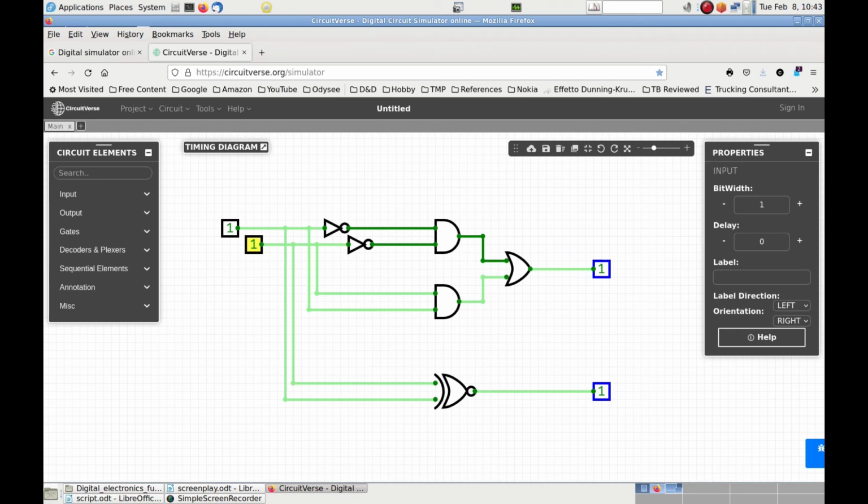Whenever you have a truth table that describes a certain logic function, it is always possible to write the boolean expression equivalent to the truth table, and from that we can finally draw the schematic for such a function. Isn't that really neat? And note also that if we have a truth table with more than 2 inputs, we can still go through the exact same procedure, just keep in mind that we will need gates with more than 2 inputs.